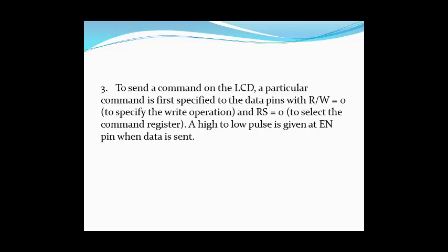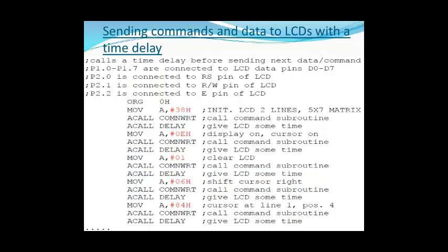Now this is a program showing how to send commands and data to the LCD with some time delay. To send any of the commands, we make pin RS equal to 0 and then send a high to low pulse to the enable pin to enable the internal latch of the LCD, and for data we make RS equal to 1.